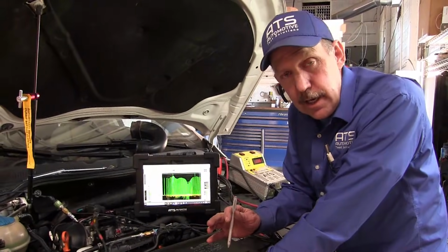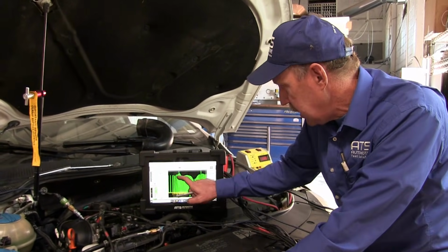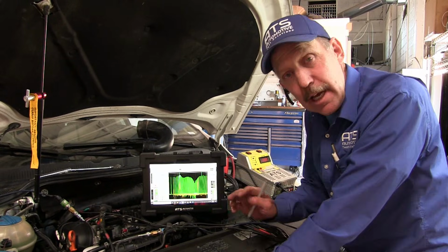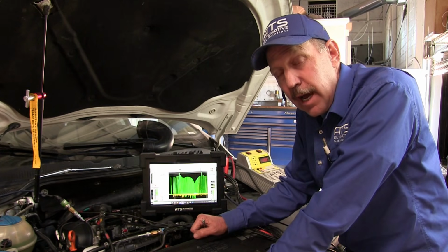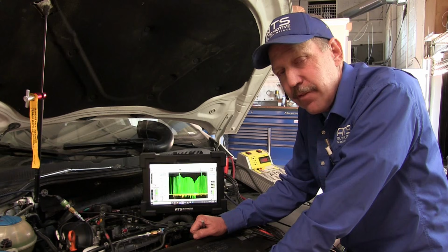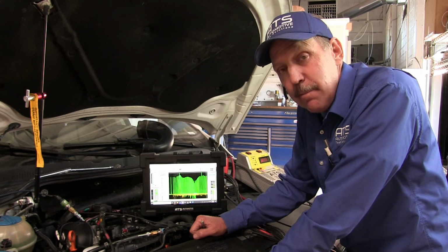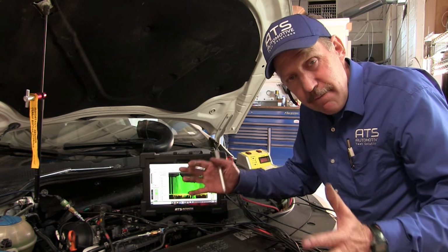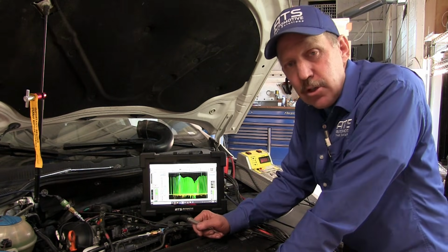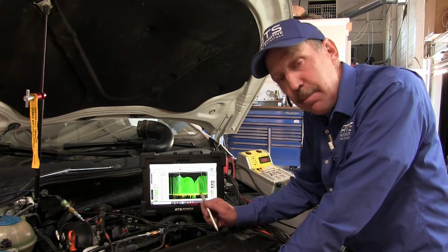So let's start the scope and get this engine running so we can gather data. Now that we have the data, we want to analyze it. The very first thing I want you to notice is we have 180 pounds at idle. To have 180 pounds at idle, I want you to ask yourself, how can you have that much air in the cylinder to get the pressure? Remember, volume is equal to pressure. If I have high volume, I have high pressure. So I had to increase the charge within the cylinder to have 180 pounds.